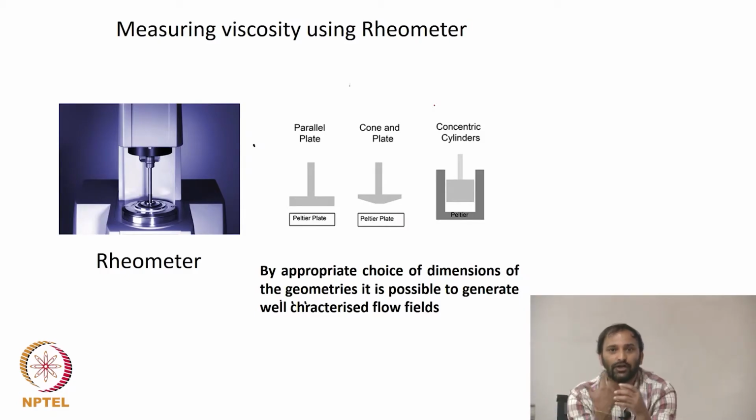At very low rotation speeds the flow looked laminar, and at some point there were instabilities. And when you do flow problems related to this, you assume some conditions, such as whether Vr is 0 or V theta is 0, and you have to figure that out.